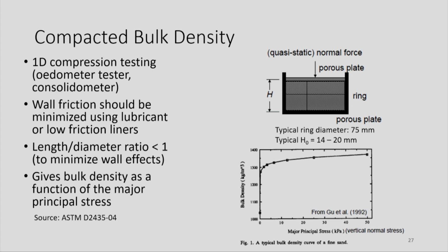Or, most commonly, you use powders, very common is magnesium stearate. It's a powder. So what they do is compact with magnesium stearate first. So it softens and smoothens the wall. And then remove the magnesium stearate compact and then you put the actual powder and compact. Then, there will be very low friction.